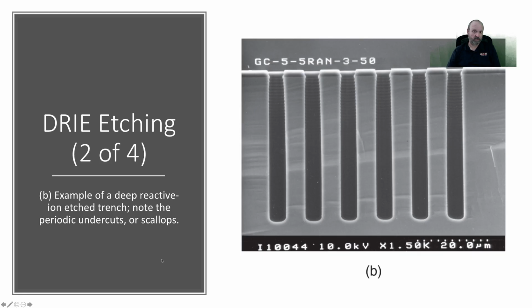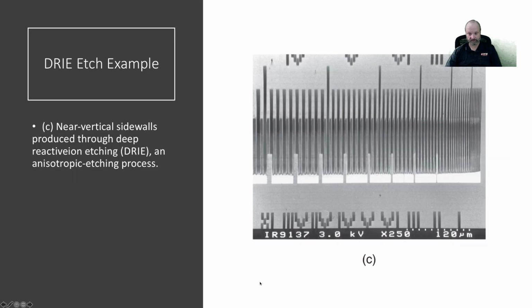So we can make the density much, much higher for the same surface area on the wafer. So now we're making smaller chips with more memory capacity on the same wafer, so we can sell them for less money. Okay? So the Bosch process allowed you to make vertically oriented capacitors to hold charge, to hold memory bits.